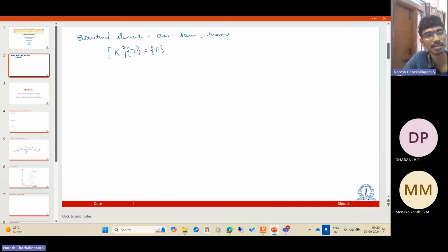So what this says is that if this is the input, we're specifying the forces and we're getting some output. And this is some reduced stiffness matrix, which has taken care of the boundary conditions and so on. So this is some kind of input to the system and this is output to system. And the input output relationship is linear. Therefore, if you multiply the force by 2 times, the displacements we get will be multiplied by 2. So the input output relationship is linear.